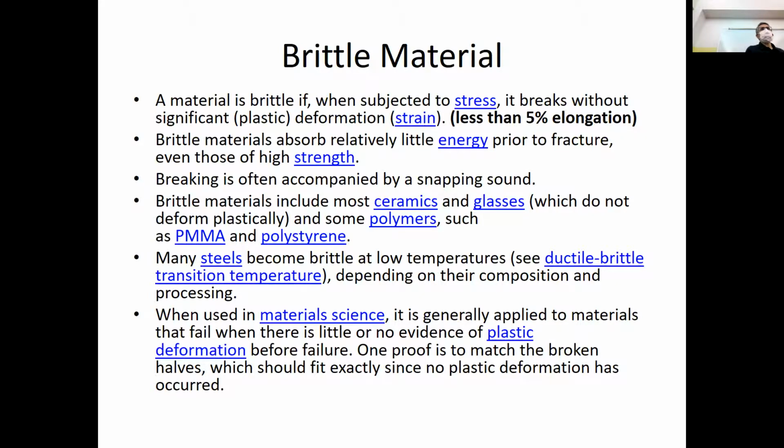A case where we always have to look at the theoretical stress concentration factor is that of parts made of brittle material, even though they may be subject to static loading only. Because with brittle material, failure occurs abruptly. So as soon as you get this elevated stress, there is no room for redistribution of the stress. The part can fail abruptly as a result of the stress concentration. So with brittle material, whether it's static loading or fatigue loading, we have to take into consideration the stress concentration.